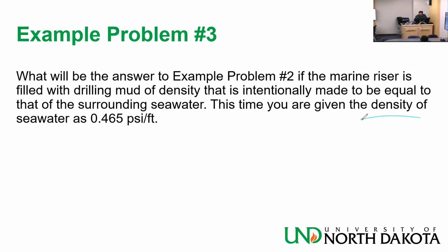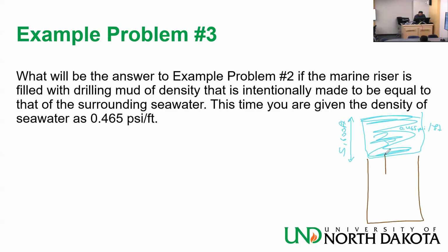So I have my seawater. It's still 5,600 feet, with 0.465 psi per foot, and I have the same well as before: 12,000 feet true vertical depth, 9.62 ppg.